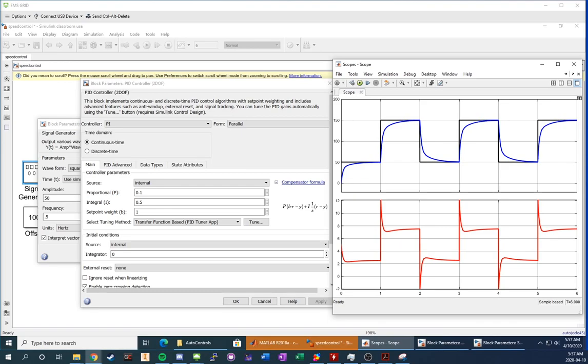Unfortunately, within the simulation, it is really hard to find oscillations that occur. So in this particular case, we are just going to be providing you with the critical gains and critical period for the proportional controller, which you can use to determine what the appropriate gains are using the Ziegler-Nichols method.